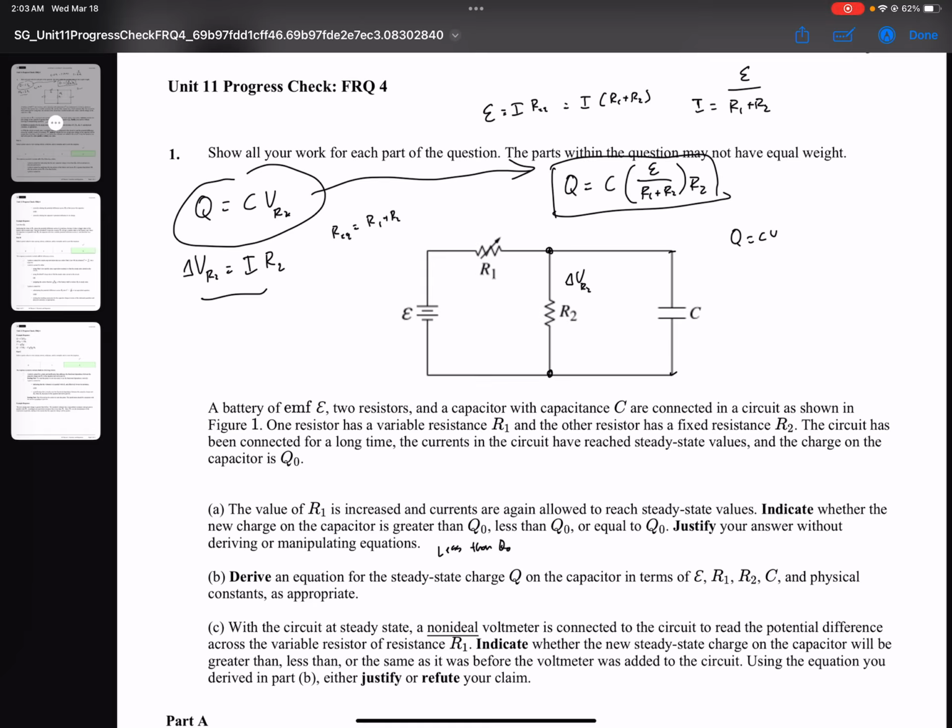All right, so just so we understand, a voltmeter has to be connected in parallel to the circuit element. An ideal voltmeter has infinite resistance, and the reason you want an ideal voltmeter to have infinite resistance is that you don't want any current to actually travel into the voltmeter. Because if there's current traveling into the voltmeter, then that's affecting the circuit.